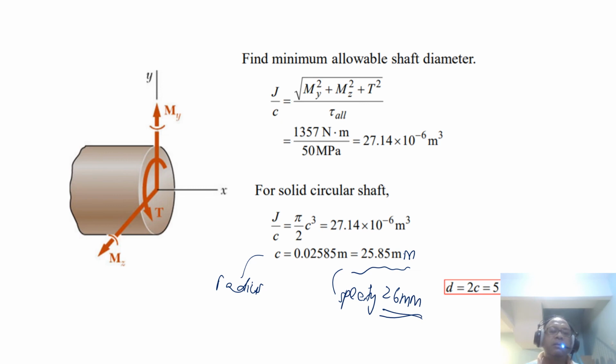As I said earlier, this is an introduction to the application of stress transformation in shaft design. It is a much more complicated topic, but we do not have the time to go into details. But I think if you have followed the lecture, you can see that we started with simple stresses, and then we combined the stresses and used the Mohr circle to find the principal stresses.